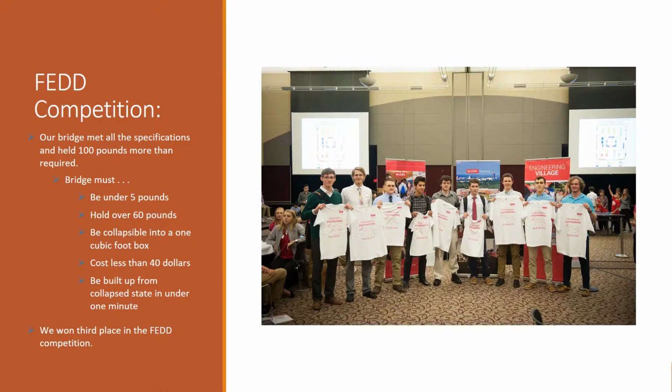Our bridge met all the FEDD specifications, which are: bridge must be under 5 pounds, hold over 60 pounds, be collapsible into a 1 cubic foot box, cost less than $40, and be built up from a collapsed state in under 1 minute. We won 3rd place in the FEDD competition, holding 100 pounds more than required.